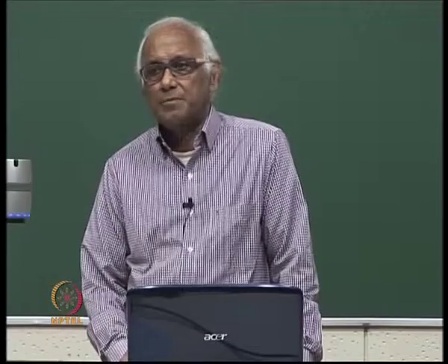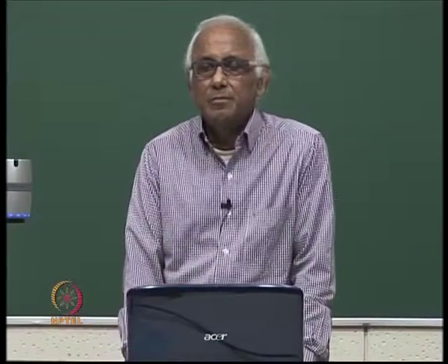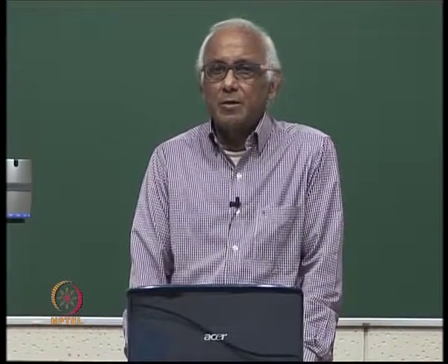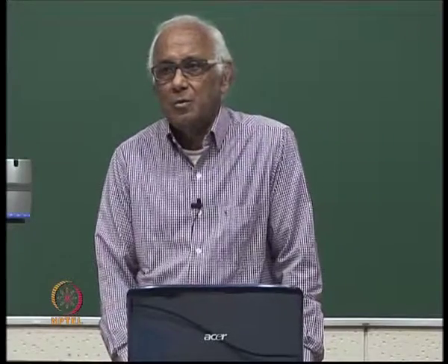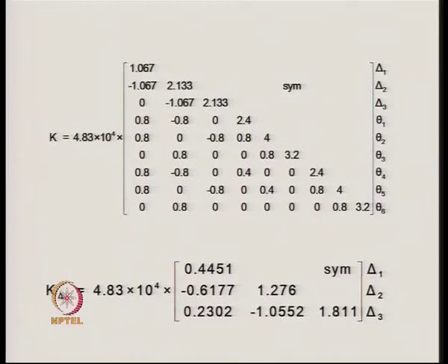Therefore, for the subsequent time interval and subsequent increment of loading, what will be done is that we will replace that plastic hinge by an ordinary hinge, which cannot take any moment. Therefore, it becomes 0. Similarly, corresponding to theta 6, we also put 0. In that same fashion, the second column, third column, fourth column have all been generated.